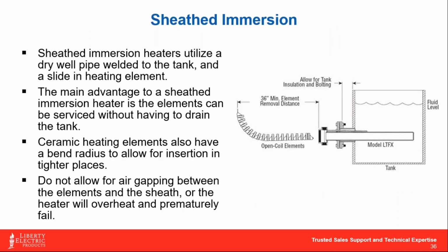This is a really interesting product as well that's often overlooked: electric heaters can be used as a sheathed immersion. Okay, and by that I mean you have a fixed protective sheath that is flange mounted to the tank itself. So if you imagine your tank with a flange coming off it, you can pop in another flange that has a dry well sheath that will insert into the tank itself, and then we can insert a heating element into it that will heat through conductive property with direct contact with that metal sheath into the water or fluid, whatever you're